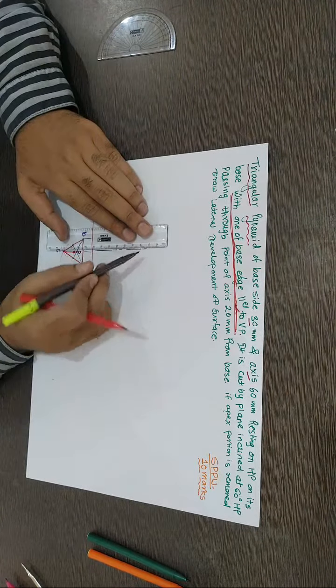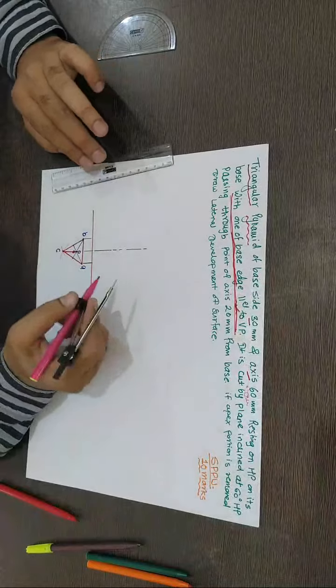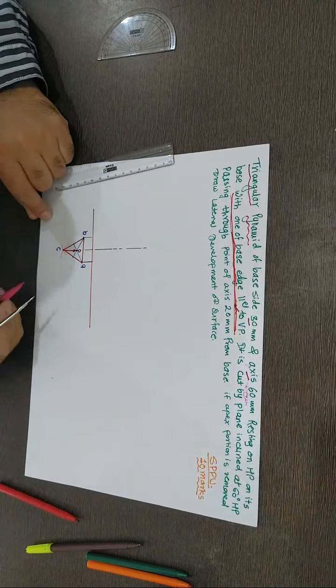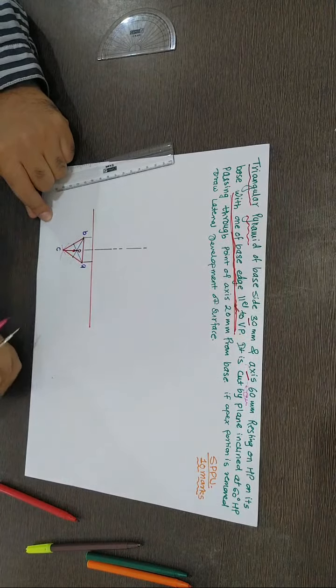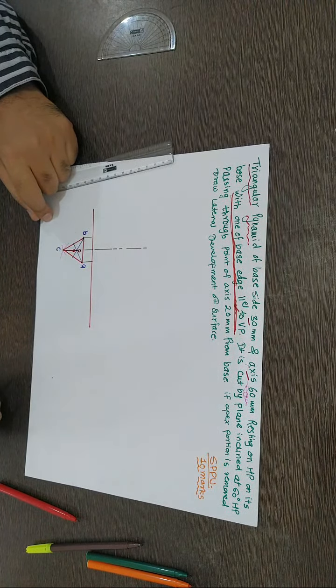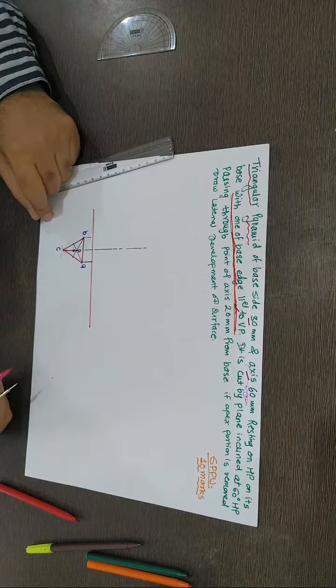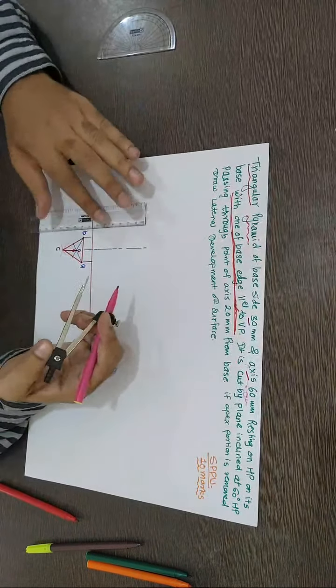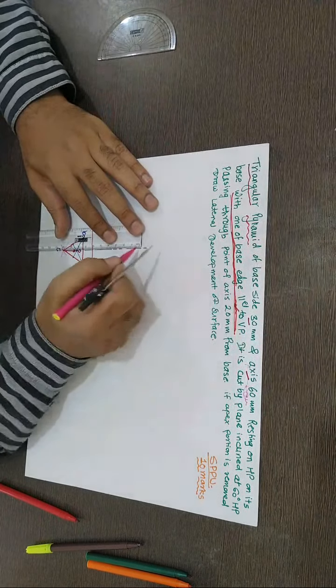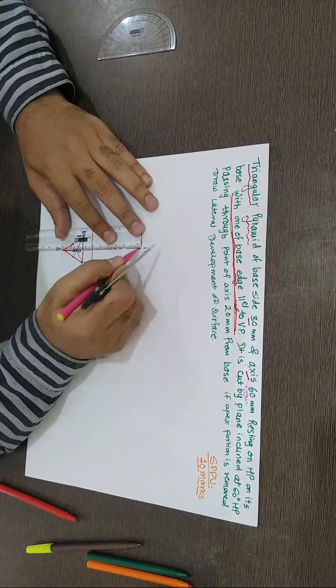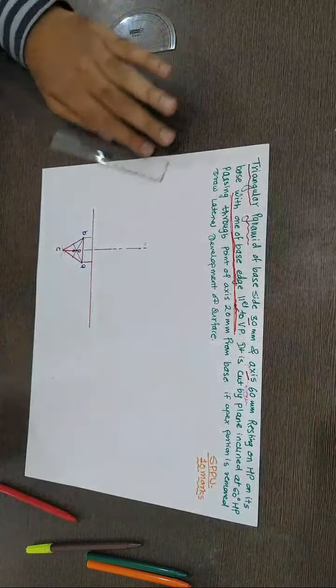Remember, the axis height is given. Again, if you want to make this problem difficult, instead of the axis height they can give you the slant edge length. We'll see how that is. If you observe OA, OB, OC, none of the slant edges is parallel to VP, I mean, not parallel to this XY line. Right now it's simple, 60 mm, so I can directly make a scale attached here. So this is 60, so this is my O point. Join it.